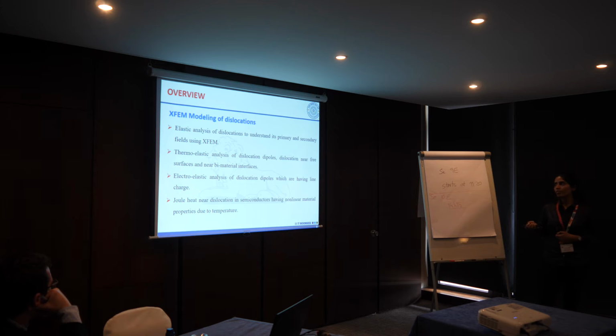Here is the overview of the work. As of now, dislocations have been modeled using the continuum concept for the elastic case for obtaining the primary and secondary fields using XFEM. Then thermoelastic analysis of dislocation dipoles, dislocations near free surfaces, and bimaterials has already been done. The contribution of continuum mechanics to dislocations was earlier started by Professor Gracie in 2007. He defined XFEM for dislocations, and then various works have been done.